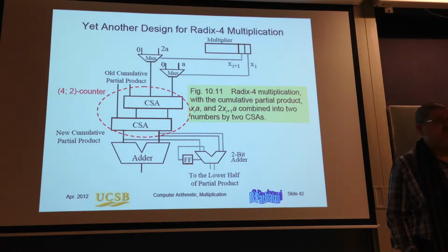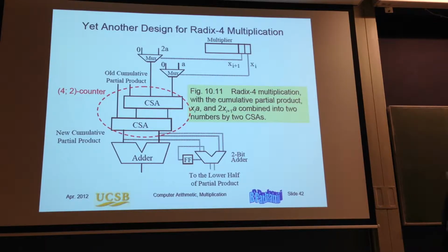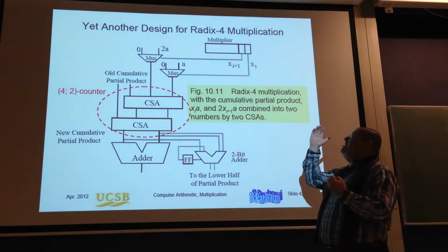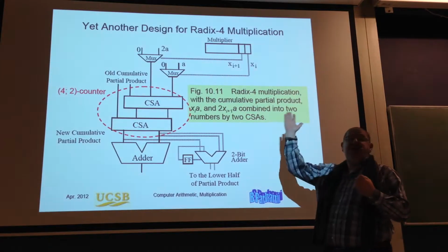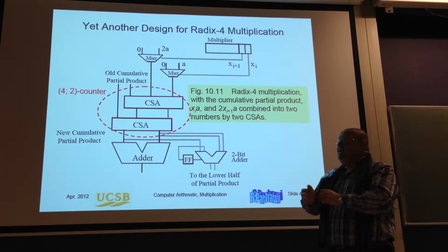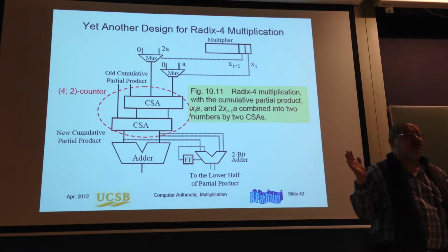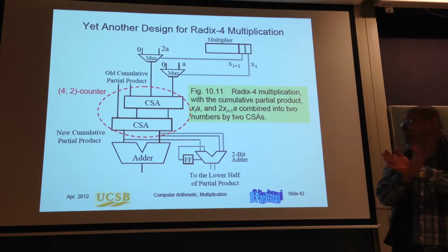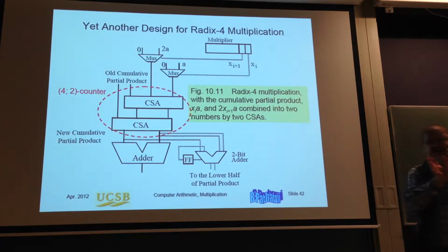And in order to deal with that, we mostly rely on multiplexers. Then you inspect bits from the multiplier, and depending on the value of those bits, you select A, 2A, 4A, 8A, if you inspect more. And then with a tree of carry save adders, you combine those numbers and obtain the right partial product. Then the second part is to accumulate those partial products between different iterations.